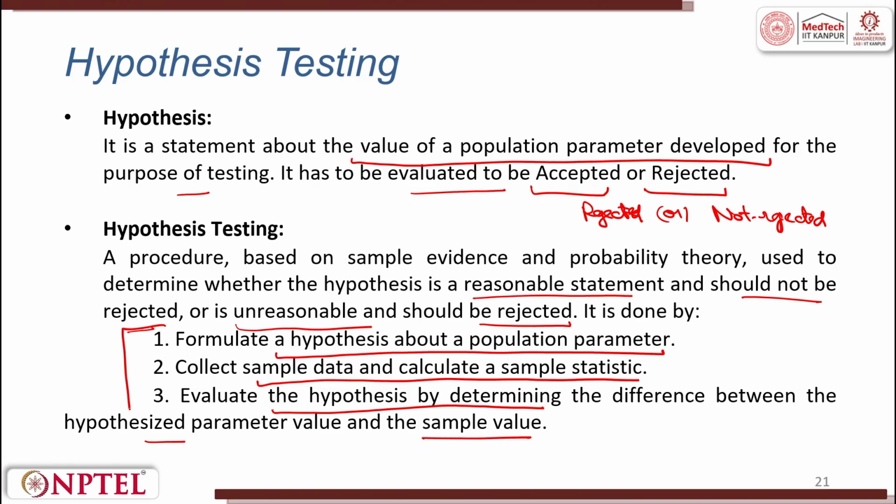We will see this through examples. Making a statement of hypothesis is very important. How clearly and how precisely we make this statement, that is very important. And there could be one-tailed and two-tailed tests. I am talking about tails because the normal distribution has ends which are called tails. A one-tailed test could be, for example, I took the example of a shaft of 3 centimeter diameter. If I say the size of the shaft is less than 3.02 centimeters, that's all, one tail, one side test only. Or if on the other side I say the size of the shaft is greater than 2.98 centimeters, that is always a one tail test.